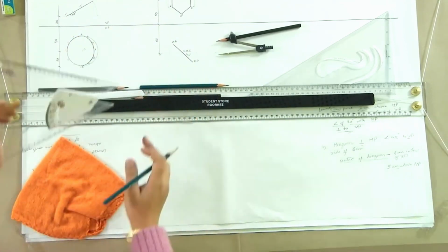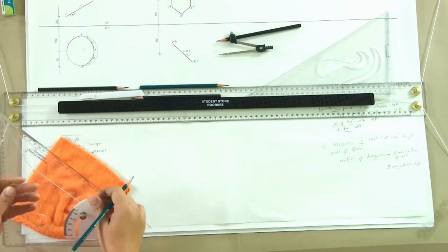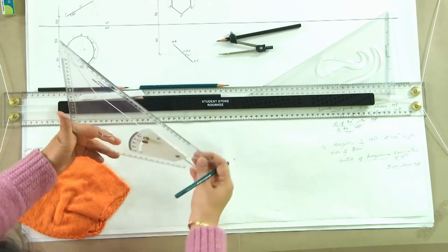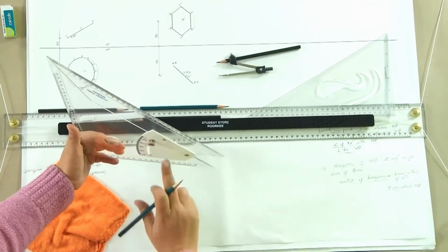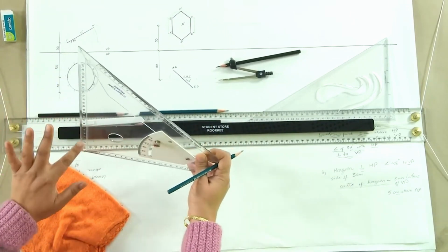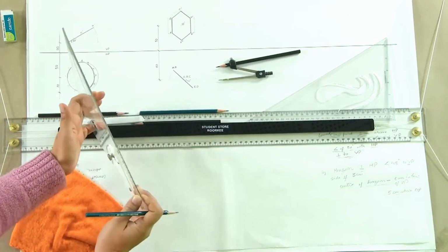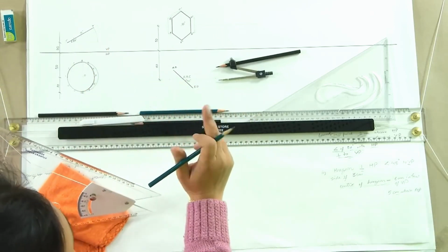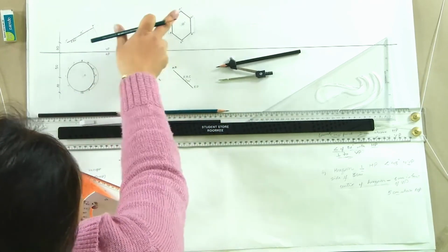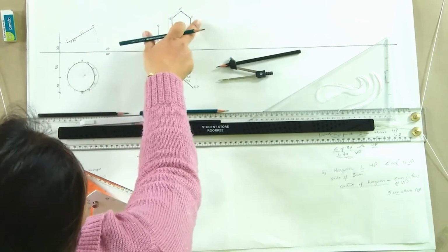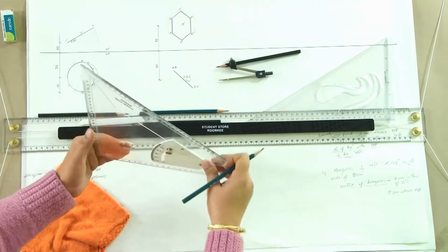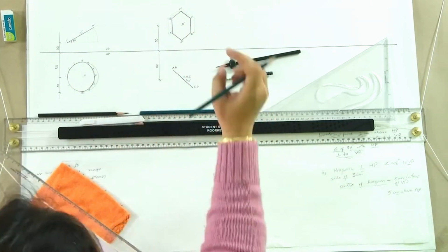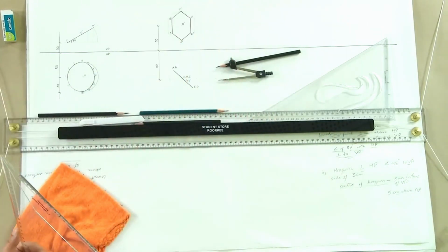The same thing happens in case of this hexagonal plane, which is assumed as parallel to VP, and now when it changes like this, each of these lines individually, not the plane, still remains parallel to the VP. So, we still see these vertical lines having the same dimension. That is why this side AB and DE, which was originally parallel to the VP, still remain parallel to the VP, and that is why we see the original dimensions there. They would still be 3 centimeters in size.